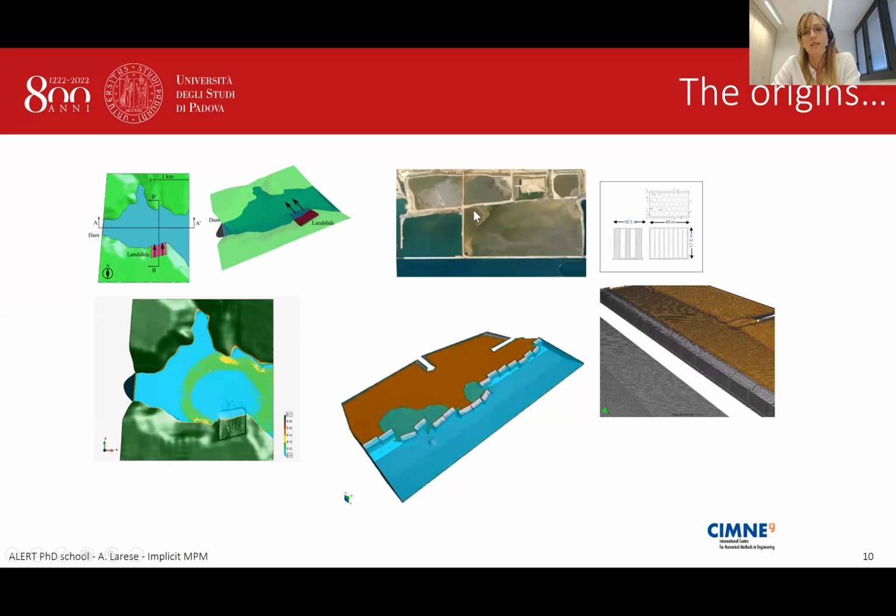They just construct the boundary of this area, and then they take sand from the sea, and they throw it here to fill in all the area, which is now full of containers, so it's completely finished. But there was a big accident on New Year's Eve, possibly due to the liquefaction of the mud inside. And basically, as you see in this simulation, these caissons were really pushed far into the sea.